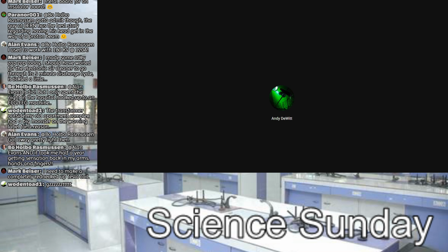I may be putting it back in, at least until I get the capacitor. I may have to order some more to make a proper bridge to get the right value. It's either too high, in which case I can't get the thing anywhere near resonance, or too low, in which case your spark gap gives you a little drizzly spark. It's not a pulse spark that'll produce the radio frequency oscillations that the coil needs to put out anything interesting. So yeah, I'll get them eventually.